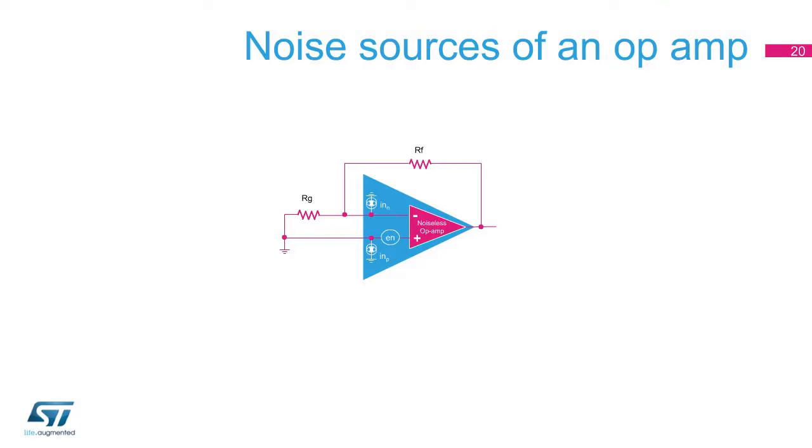The easiest approach is to think of it being in the frequency domain, even if engineers generally prefer the time domain. All internal sources of noise contribute to the overall noise generated by the operational amplifier. The op-amp noise is modeled with 3 noise sources. One source for the input noise voltage, or EN, and 2 sources for the input noise current, or IN. A current issued from a current noise source and flowing into a resistor generates voltage noise according to Ohm's law. All sources are physically independent and therefore uncorrelated.